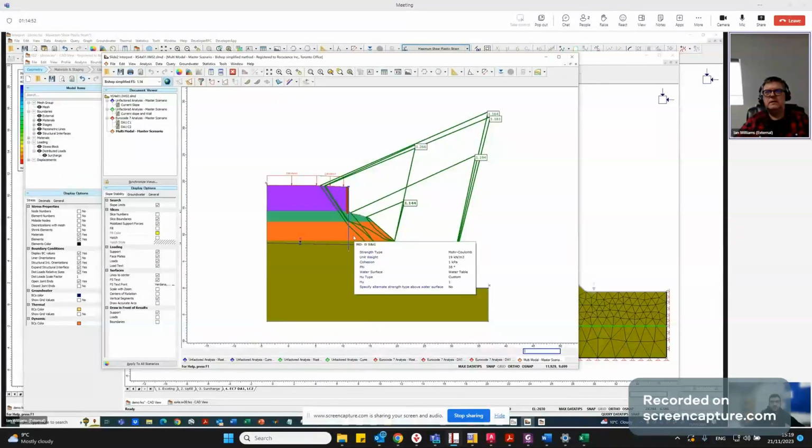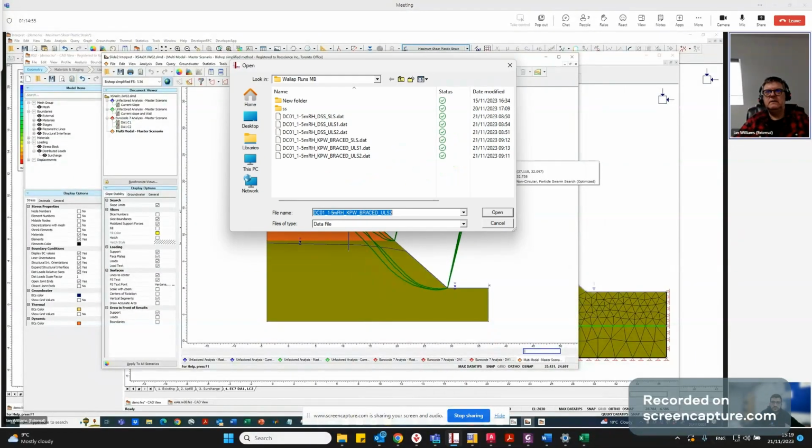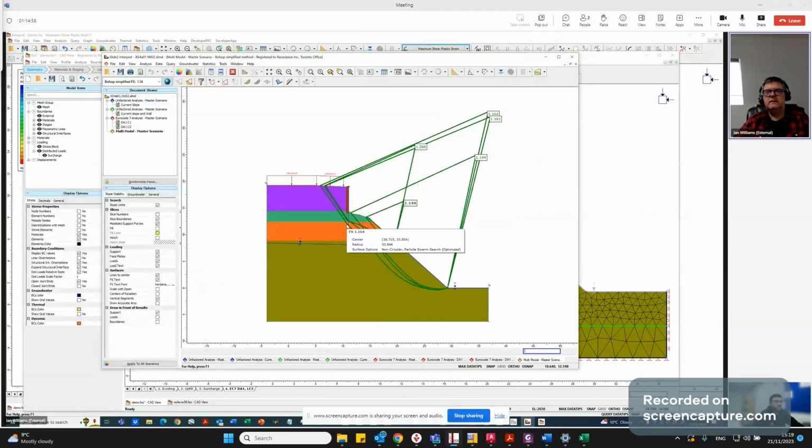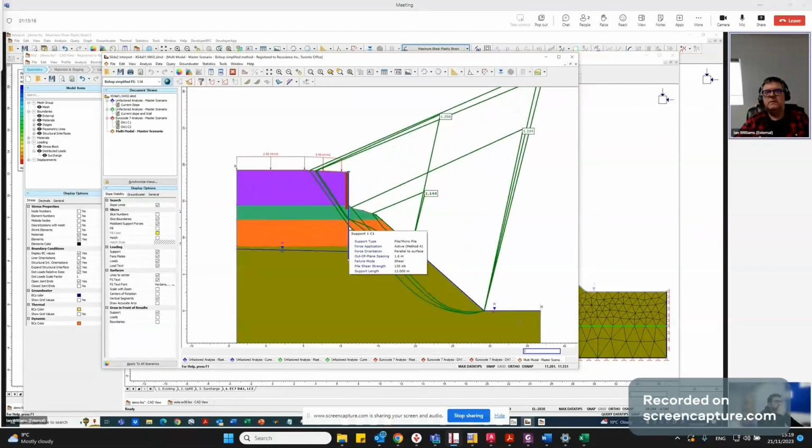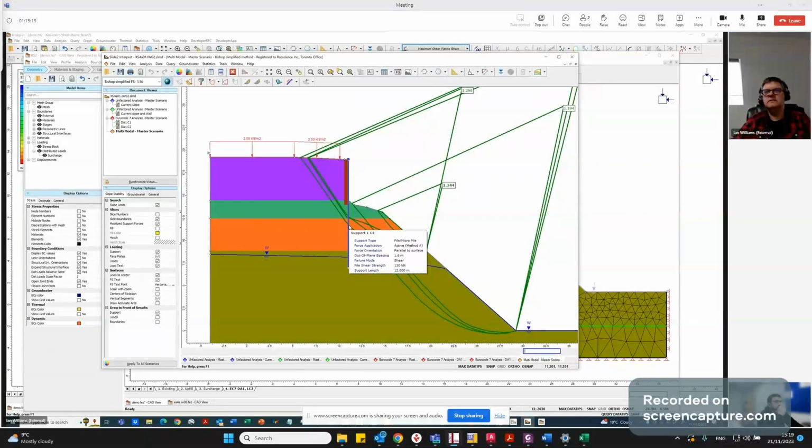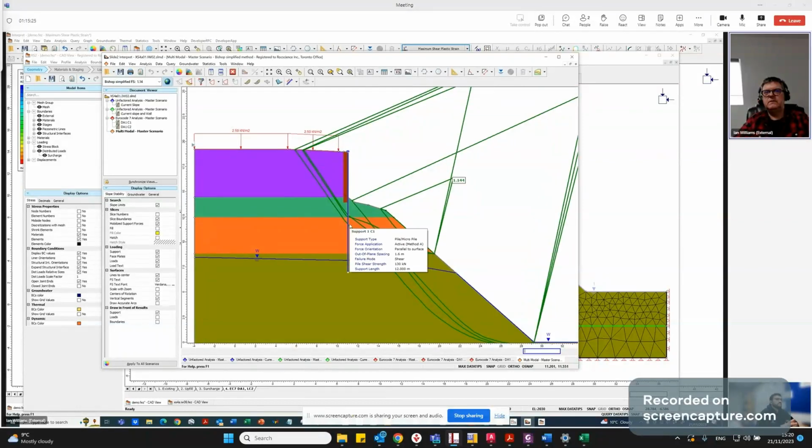You've got quite different factors of safety here, significantly higher. So what's the retained height? Again, it's because of the way that it's affecting the top of the slope, isn't it? All this pile is doing is shoving in a shear stiffness at this point. So it's just putting in a horizontal load, so it's not onto the slice where the slip surface intercepts it.